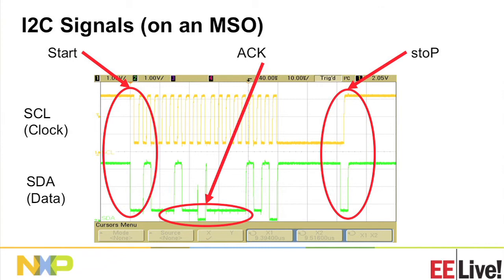Now, you'll also see some spikes on the diagram. My pointer does not work on a TV screen, so I'll use my dirty fingernail. There's two spikes here. Those are caused by the bus changing direction. During the time that it changes direction, there's some uncertainty about the actual signal levels, which is why we built dead time into the spec originally.